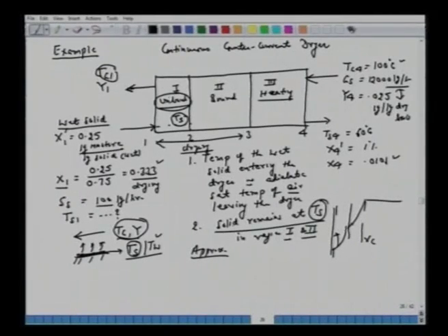All right. So those are two rigorous assumptions we have made here for our calculations, but you will notice that the first one for the region 1 is a very good assumption. For the region 2, bound moisture, maybe if it reaches this capillary region, then it's possible that there will be some error there. All right. Nonetheless, after it has reached this first unbound region, the moisture content is now Xc, and the problem says Xc is given to us, its value is 0.087.